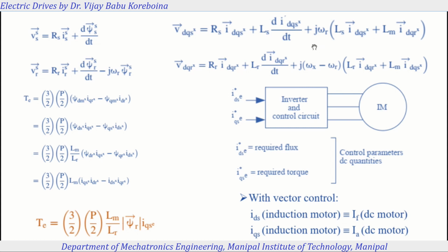That means three-phase currents are transferred to IDQ, three-phase voltages are transferred to VDQ. Likewise, the three-phase flux is also reduced to phi d and phi q. So the components are reduced from three-phase coordinates to two-phase. By this, what will happen? The torque produced, from the derivation, is a flux dependent component as well as a current dependent component.